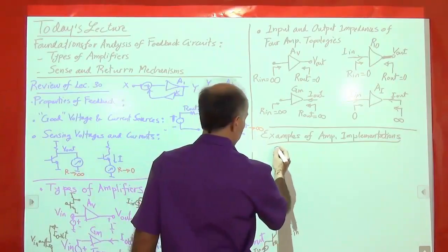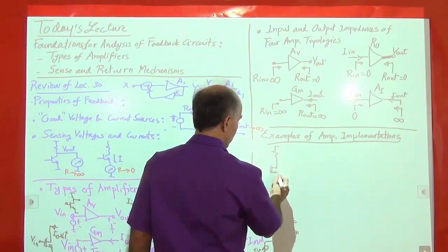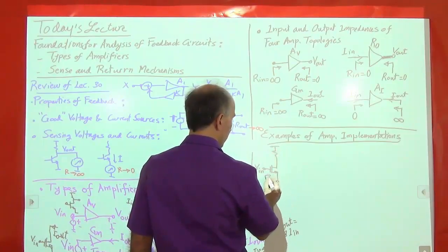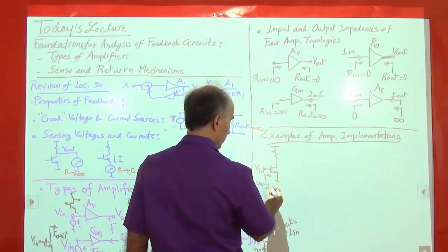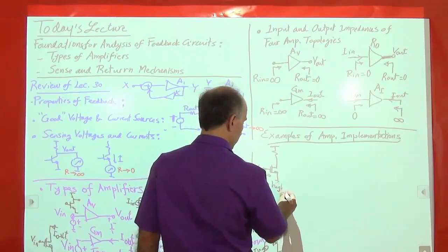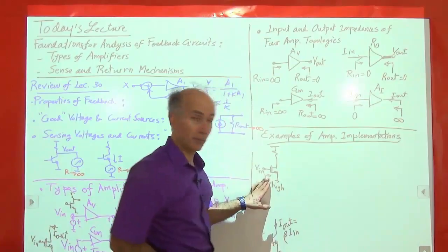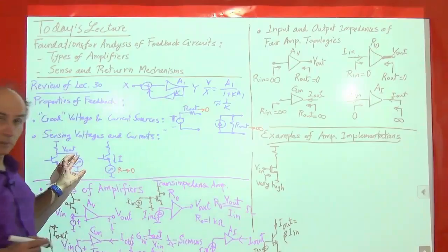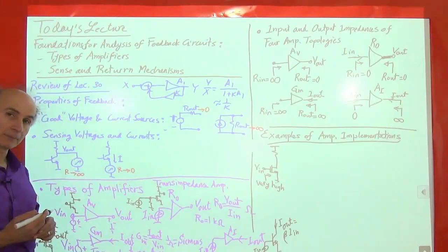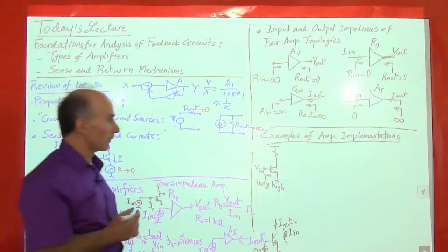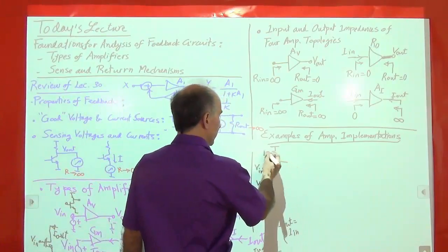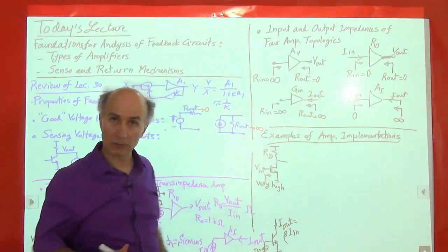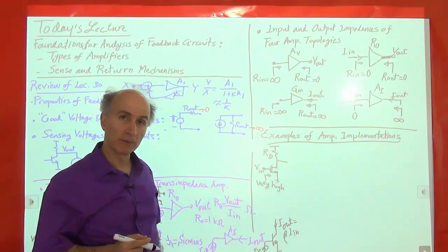So here's a common source transistor that senses a voltage, and its input impedance is very high, right? So I'll just say very high. So that's a very good mechanism for sensing a voltage, right? We are sensing it just like this voltmeter with a high impedance. Okay, but the output impedance is not that low, right? This is RD. I was looking for a very low output impedance, but this is like some kilo ohms or hundreds of ohms. So what do we do?